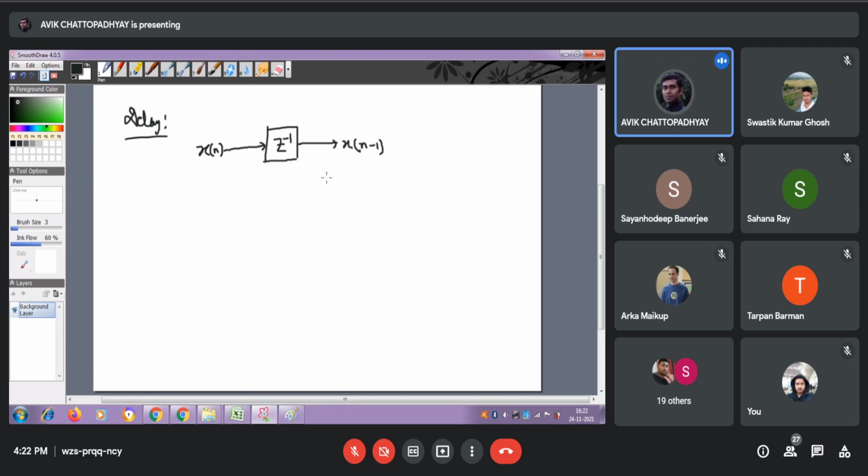So that is why we have to use this symbol. Now please note, try to relate minus 1. This inverse actually indicates a delay by one sample. Okay, now suppose instead of minus 1, if we write minus 2, then probably you can already have understood that it will be delayed by 2 samples.